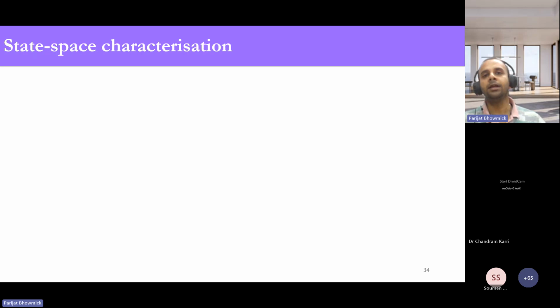But suppose you are given a very complicated system, a 10th order system or a 20th order system. First of all, it will be very hectic and tedious to do all those calculations by pen and paper. If you tell me, okay, I have MATLAB, then for all LTI SISO systems we can find the NI property by looking at the polar plot. But what will happen if you are given a MIMO system, a multivariable system? In that case we cannot apply the Nyquist plot directly. Then how do we find out the NI or SNI property?